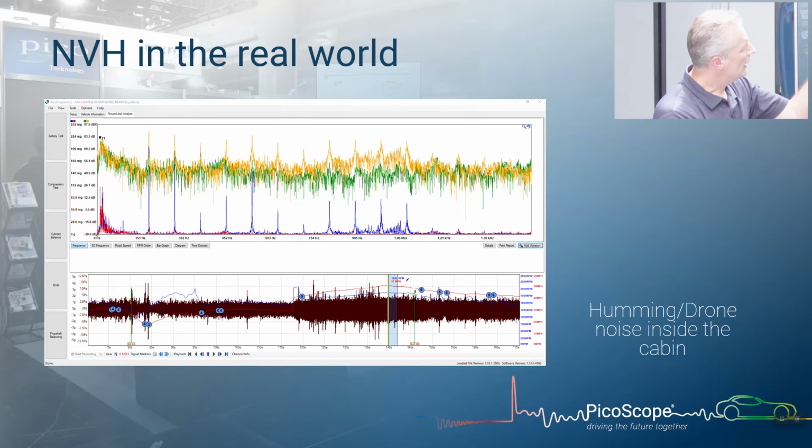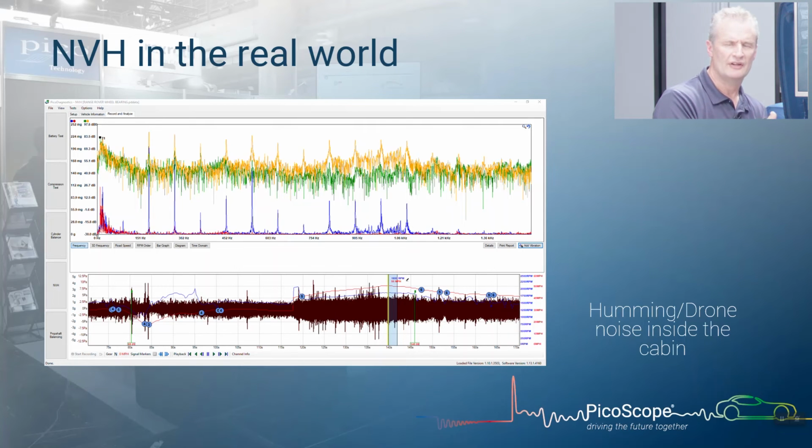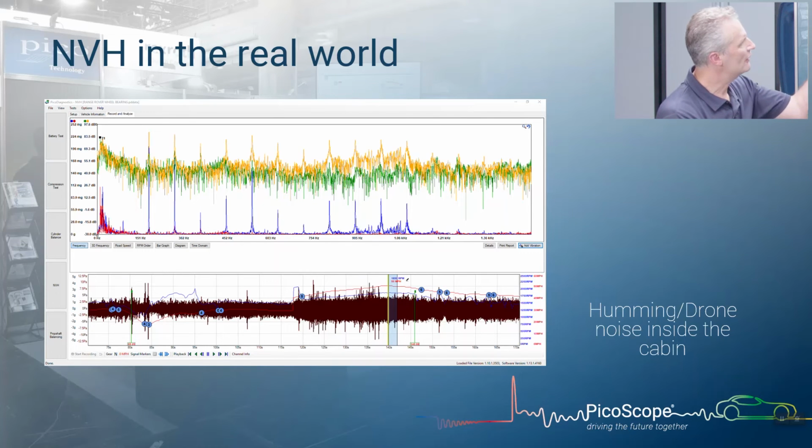So how on earth do we use those multiple harmonics? There's no one single frequency associated with a bearing when you get the degree of wear that you're about to see on the next slide. If you can imagine a tin can connected to the back of your vehicle being dragged along the road, the amount of deformation and clattering noises that it would make, there'd be no uniformity to it, it would just be sporadic, and these are the type of harmonics that you will see.